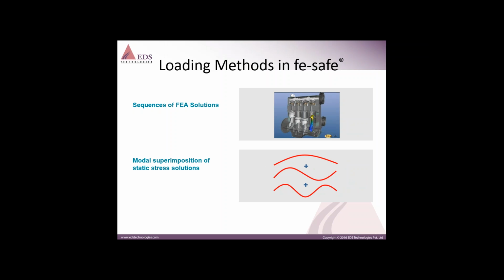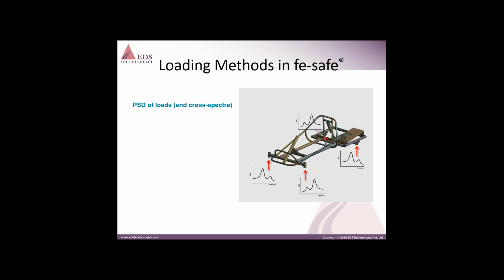It can support a sequence of FEA solutions. You can see the example on the right-hand side. Similarly, modal superposition is also one of the loading methods in FE-SAFE. This is PSD fatigue, or vibration type of fatigue, wherein the PSD curve will be your loading.